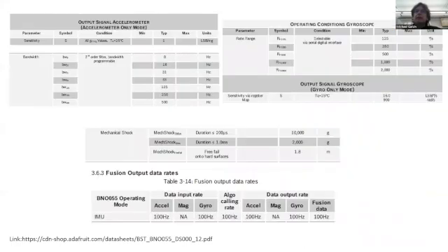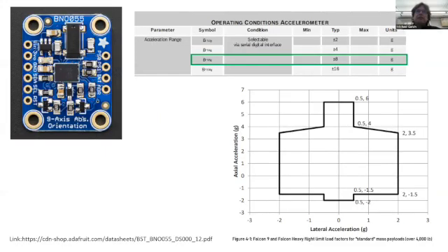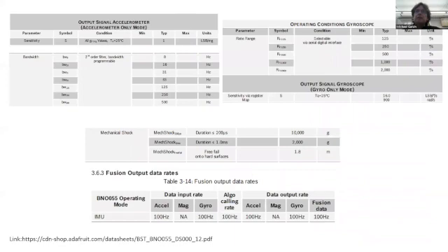So using the Adafruit BNO 055, there's a lot of other user configurable options that you set up in code during the initialization of the accelerometer and the IMU and the gyroscope and the magnetometers. And the practical application of what we're talking about here is making sure that you preset your measurable ranges in your accelerometers to ranges appropriate to your mission.